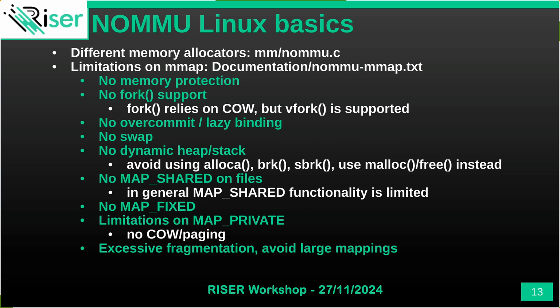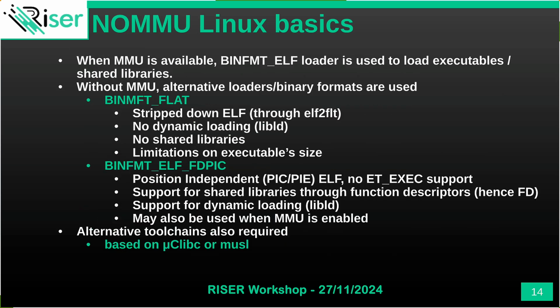If you want to test, for example, the PCIe driver, okay, you can write a bare metal test for it. It will be very complicated. If you just run no-MMU Linux there and you use the driver that's already in there, it's much simpler. And for you, it's way less work. But you still can do lots of stuff even with those limitations.